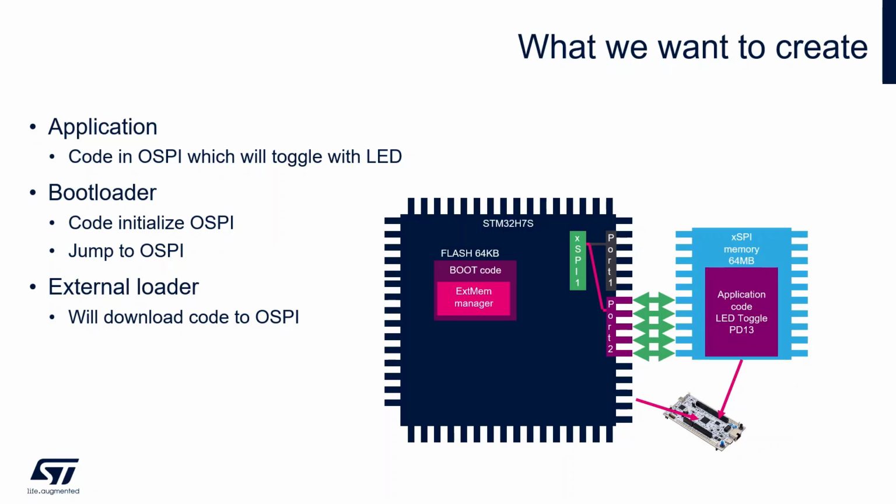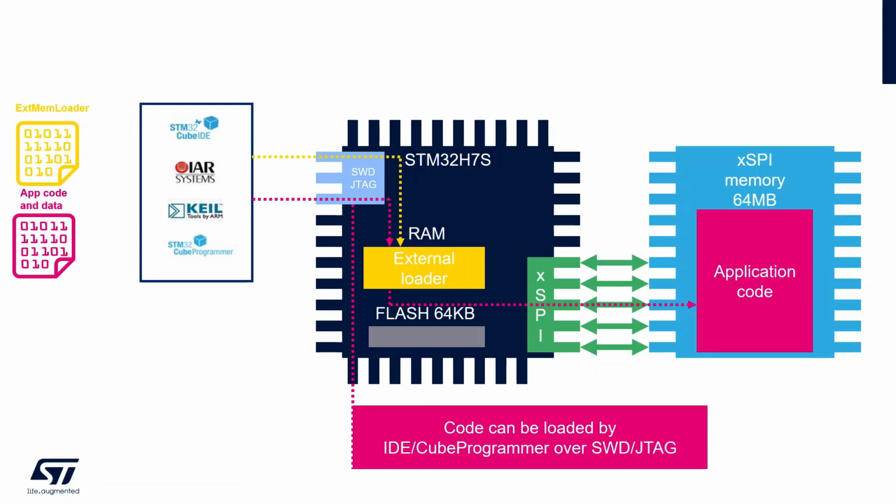And the last part will be the external loader, which is not directly used all the time on our microcontroller, but it's mainly for our Cube IDE or Cube programmer, to teach it how to download the data onto the external memory. About the external memory loader, if you're using the internal memory inside the STM32, we already know this memory, or all the manufacturers know their device and its memory, so we already prepared this project.